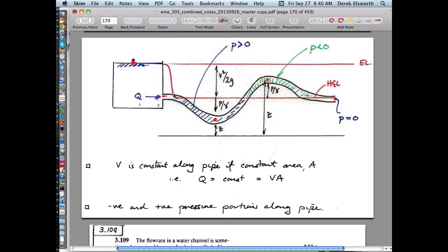So as you come out of this pipe, you're accelerating the fluid, which has 0 velocity initially. At some close place to the entry, it has some bigger velocity, up to the velocity that it would have. It has the same flow rate here, so the velocity isn't changing as you go. You could imagine, if you like, that this could be precipitous, it could be vertical, but the reality is it'll take a certain amount of length to accelerate. And so as you go along here, the velocity is constant along this pipe, and so the component of the velocity head, the kinetic term, also has to be constant. This height here has to be constant all the way along here. And so you know that.